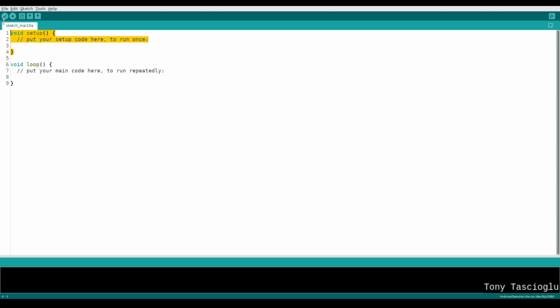So your program has two essential parts to it. You have a void setup and you have a void loop. So essentially, here's the difference. In your program, when you upload this, the Arduino first starts up, it starts going through your code, right? You can actually have stuff above void setup, like variable declaration. I'll go through that later though, probably in my first example.